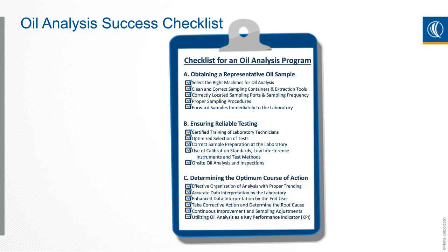These are things that you may be doing in your own plant with some type of oil analysis, maybe using a vis gauge for some viscosity testing or something else that's more simple. But even the visual inspections you're doing on your machines can provide very important information to combine with what you're doing in oil analysis to give you a better interpretation as a result.